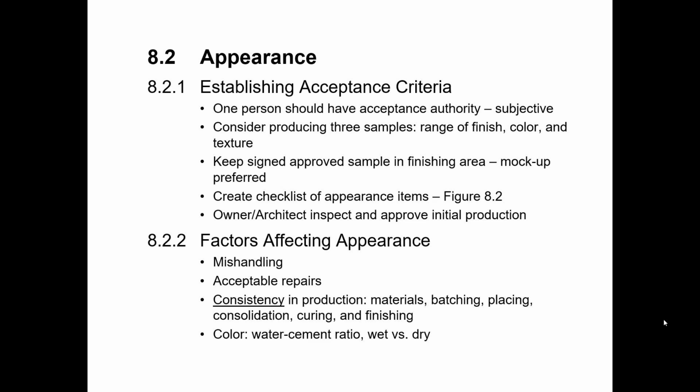Contrast that with the variations you get from a wet versus a dry condition. Those same 4 samples are given at the bottom, but they are saturated, so they're in a wet condition, and you can see even the 0.3 gets even darker. Even though it was already dark before, it gets even darker, and the others go from a very light gray to a much darker gray, just depending on how wet or saturated the concrete is. So we bring that up to say that time and environmental conditions need to be considered when decisions are being made on the final appearance of a product.